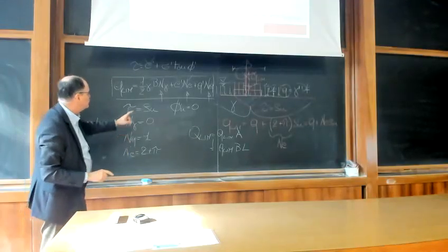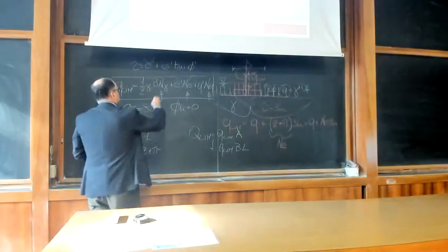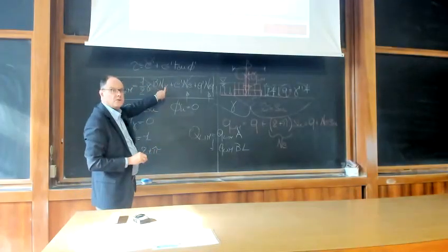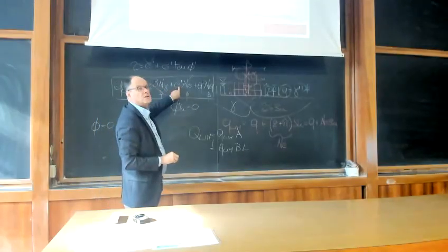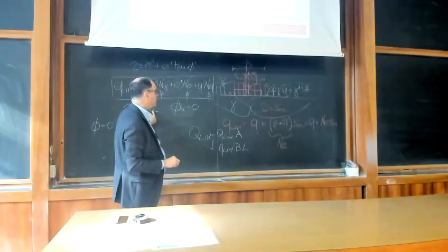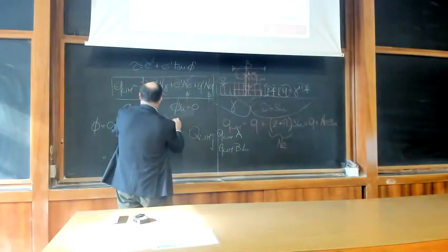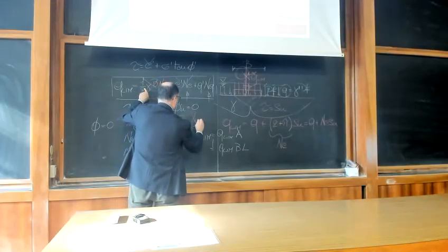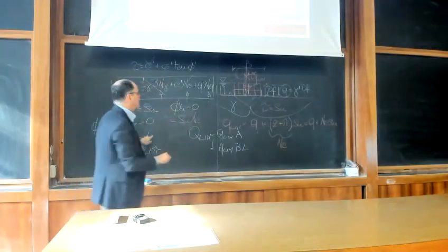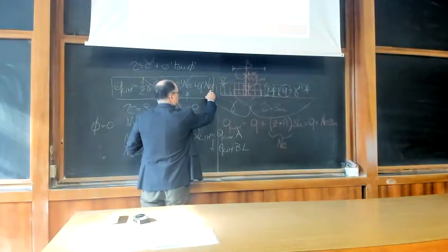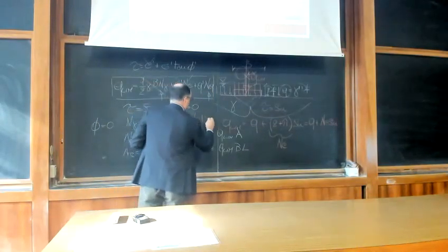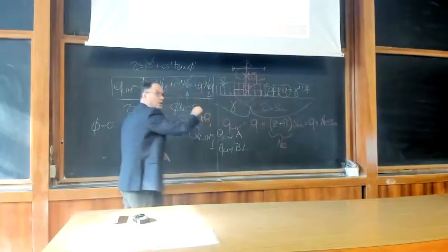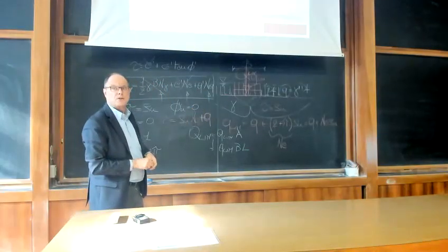So you see that in undrained terms, this is 0, not because gamma is 0, because this comes 0. This is no longer C prime, but it's the undrained shear strength. So you have this 0, you have Su and Nc, which is almost 2 plus pi, plus, this is 1, and you have some q. q is no longer q dash, it's the total overburden stress.